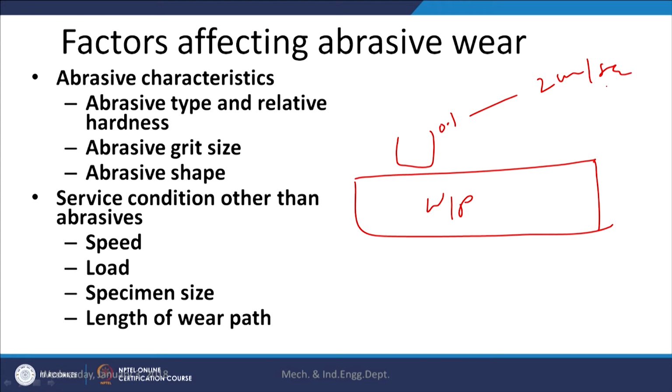When the abrasive is moving at different speeds with respect to the workpiece, accordingly the material present at the surface will be affected by deformation or work hardening, because whenever the abrasive load is applied through the abrasives, the material will be deformed plastically, and will in turn experience work hardening. So, near surface layers will always be experiencing deformation as well as work hardening. So, work hardened material will have its own effect.